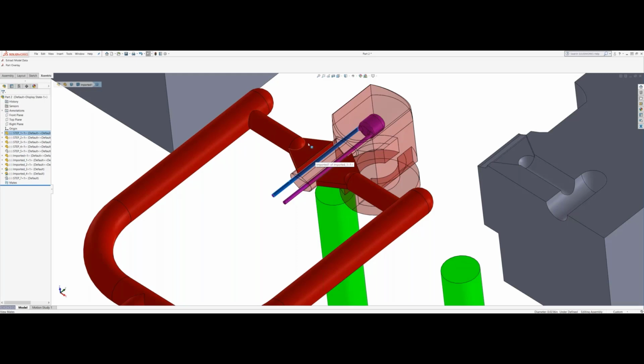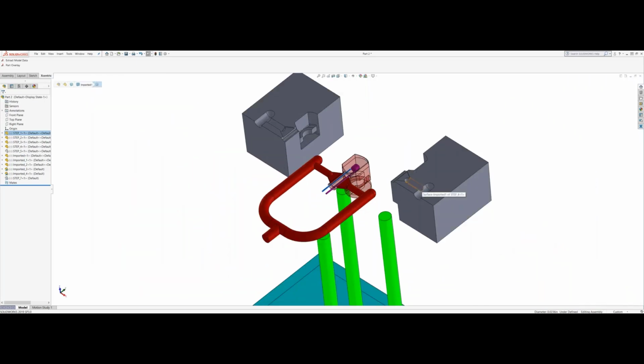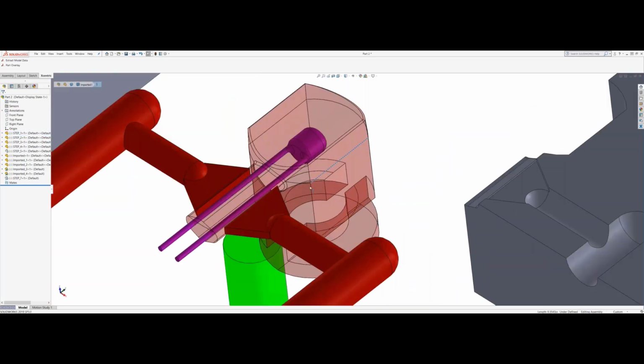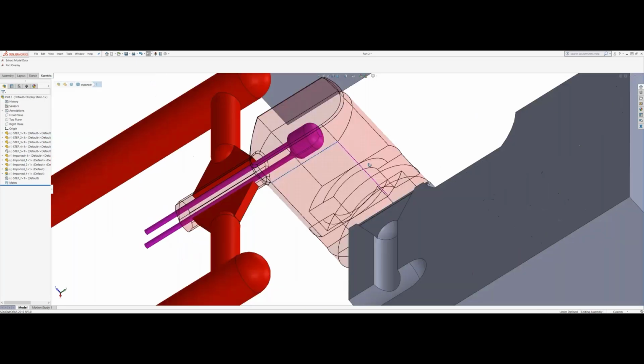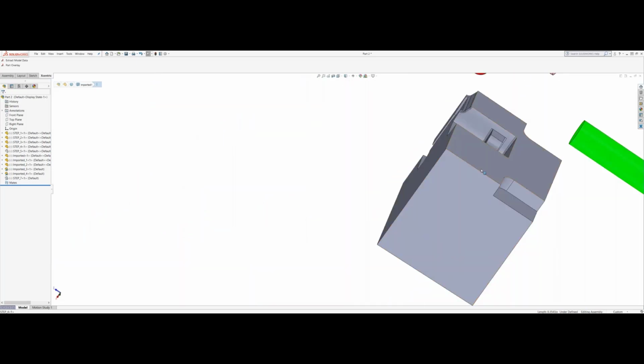All right. Did you have any venting, and if so, where? We really don't show it in here, but it's going to mainly be around parting lines, core and cavity. In this case, the main parting line was this line here around, and then obviously a split between the part down this length here. That's kind of a natural opportunity, where all these split lines are, and it provides us an opportunity to vent if need be.